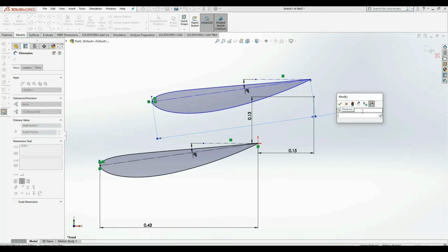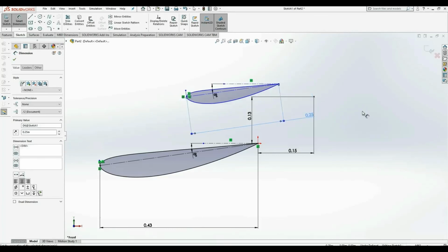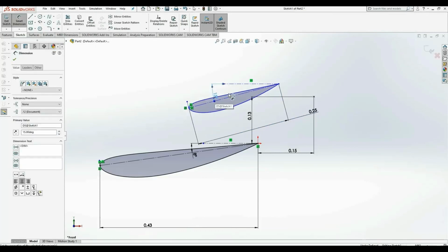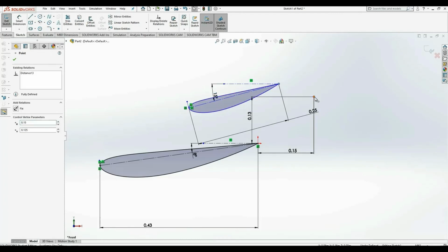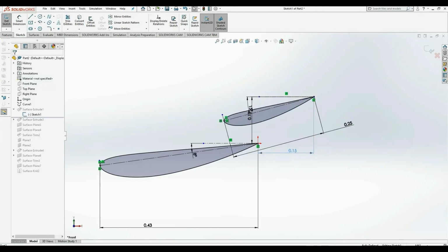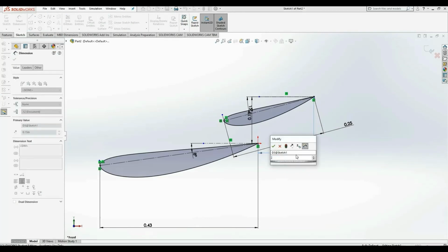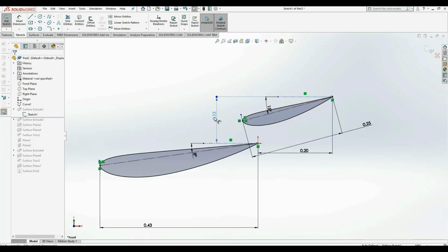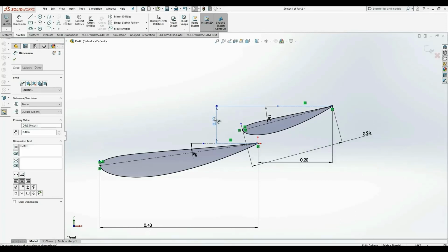So let's obviously the second element, much smaller. I'm not sure whether these dimensions are going to work at this point. It's a bit of trial and error, but there's nothing wrong with a bit of trial and error if we get it set up right. So angle of attack is usually more for the second element than the primary element. Attaching that trailing edge point to my new point set in space. Now I don't necessarily need to change the dimensions of my aerofoil, I can just change the distance in which that point is acting. I want to see an overlap.